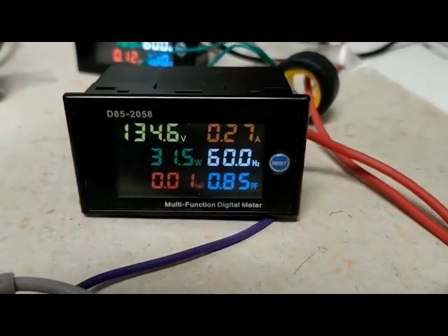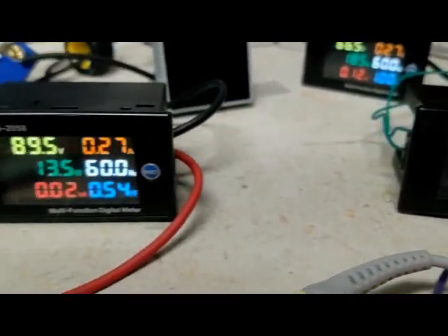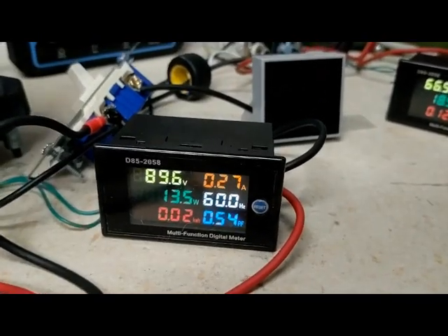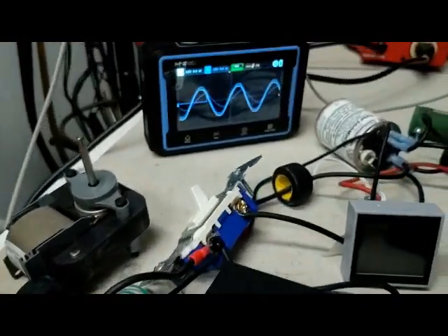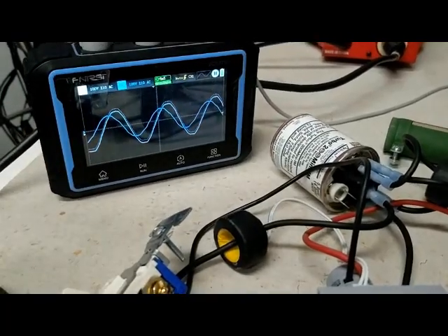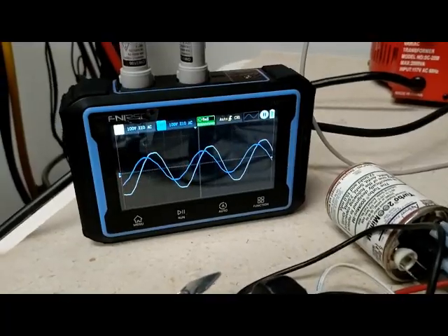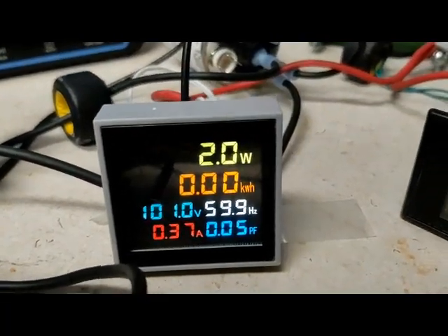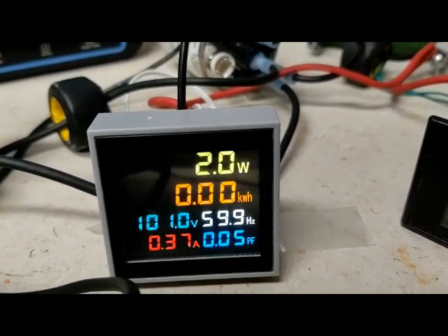The power factor on the overall circuit, though, has gone down because now we have this low power factor device included in the circuit. Now let's take the motor back out and bring the capacitor in. And now the current is peaking before the voltage.